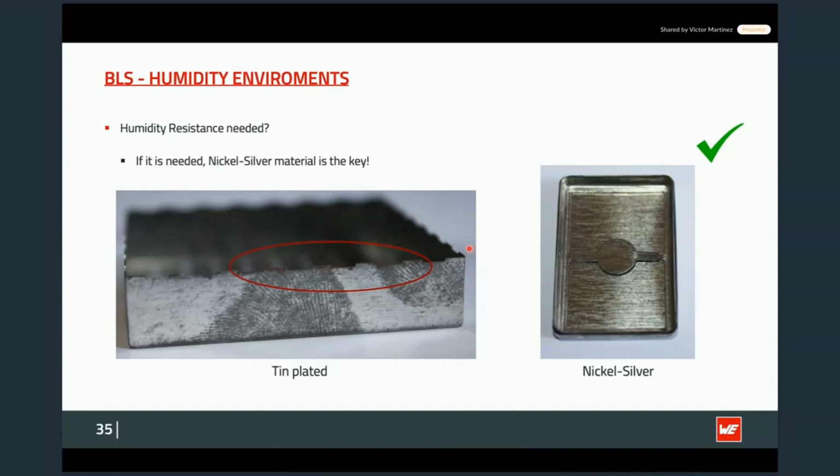This oxidation problem won't affect, in this case, the shielding effectiveness. It will only provoke two side effects. The first one is that it will be more difficult to solder it to the PCB. And the second one is that it won't look as good to the end customer. As we commented before, the end customers want something that is colorful, stylish, polished, and looks good to the eye. And if it is oxidated, probably they will think that it is not as good as some other brand new product. But the main thing is that it won't affect the shielding performance of the cabinet.